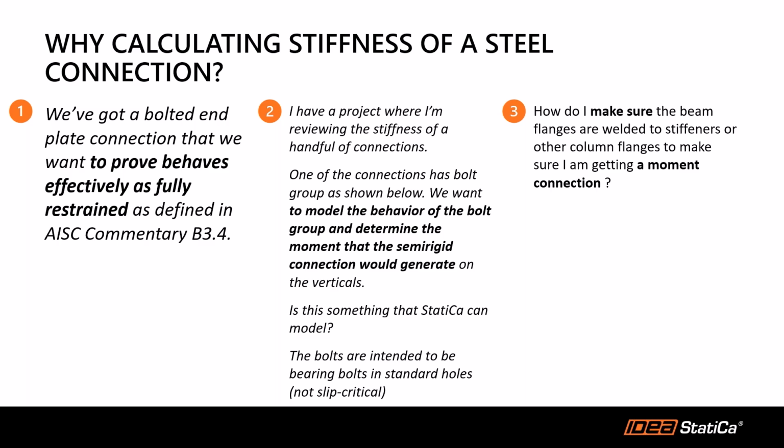You have that experience, but it's not until you run the stiffness analysis that you really know whether this is a moment connection or not. So again, this was a modeling question, but our suggestion was also to run a stiffness analysis so he can be sure that he had a moment connection.